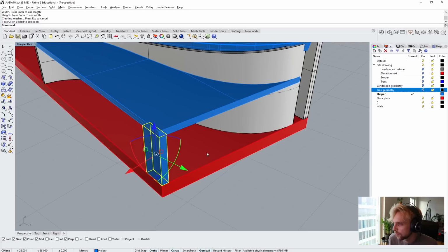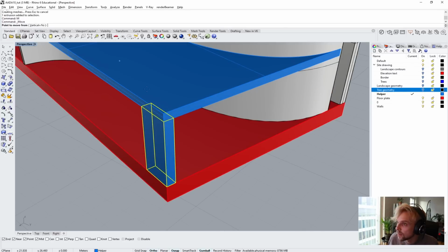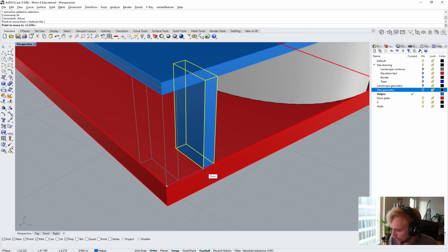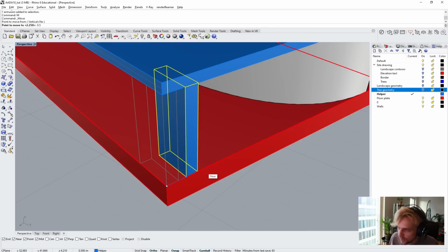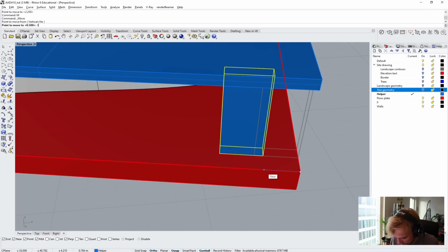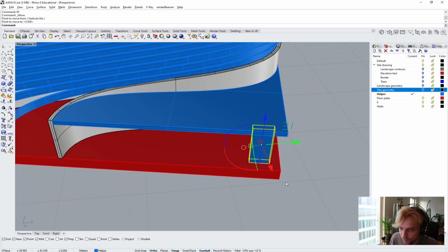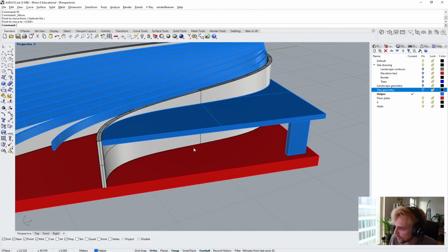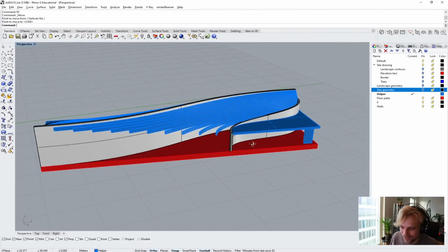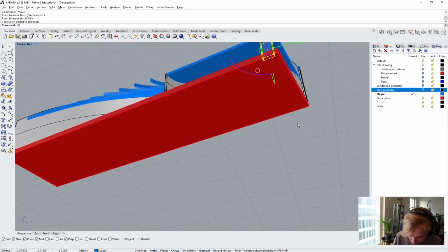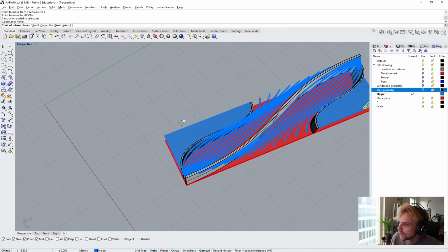or roof slab. And then I will take this shape, this column shape, and I'll move it in by 0.5, by half a meter here. And also I will move it in by 0.5, by half a meter, like so. Right? So now at least this roof is being held by something, right? And then I will take this column and I will use mirror, and I'll mirror this column to the other